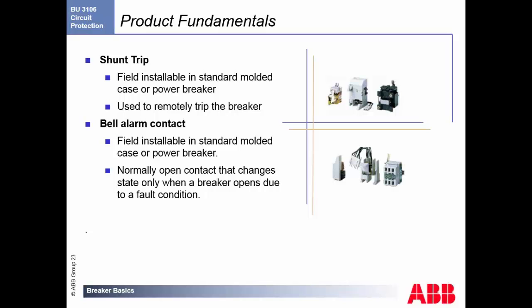A bell alarm, again, field installable. Basically, it just lets you know the state of the breaker so that if you're in a remote area, you can hear that the breaker opened and know that the power has been cut down to whatever branch, main, or feeder that you have down the line. Again, we're trying to remove the aspect of anybody going towards the breaker without having the proper PPE, which requires a half an hour of suiting up and sending a guy out there. We want to make it so that you can remotely tell what the breaker is doing, and we have trip units that actually can tell you why it did what it did.